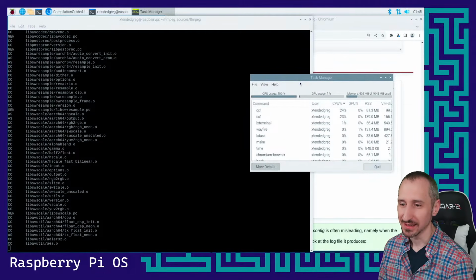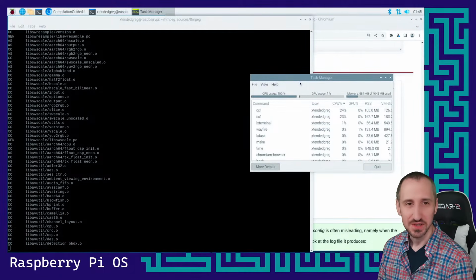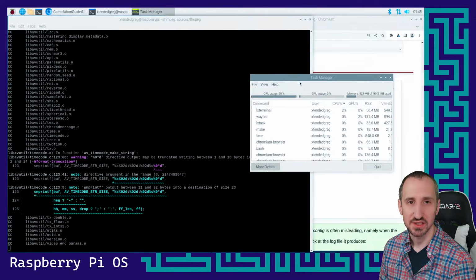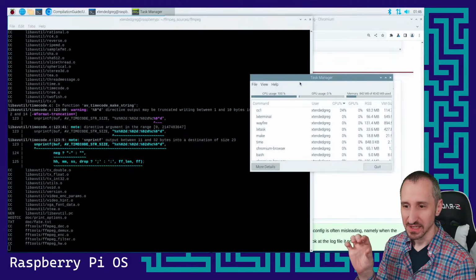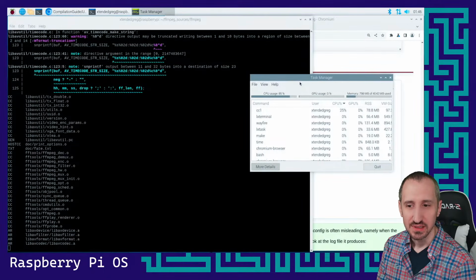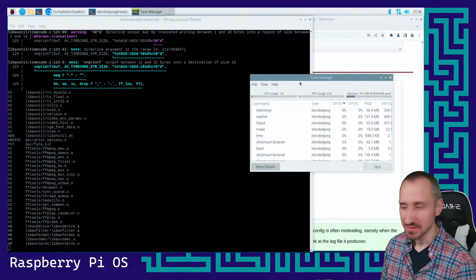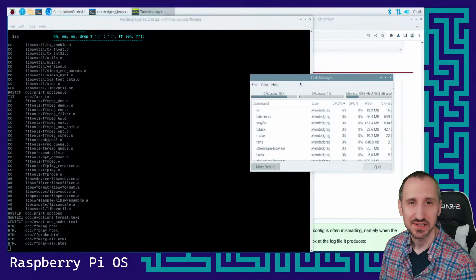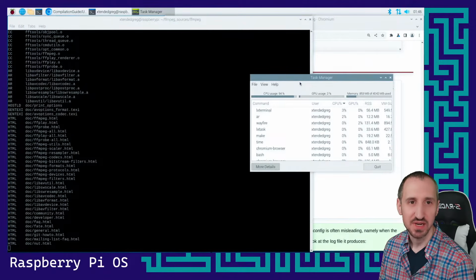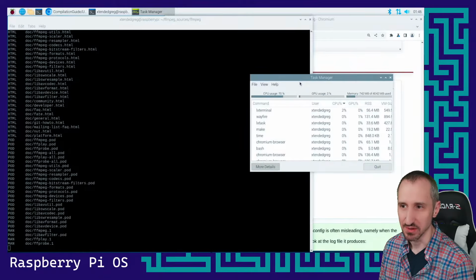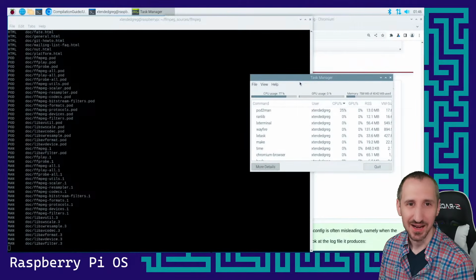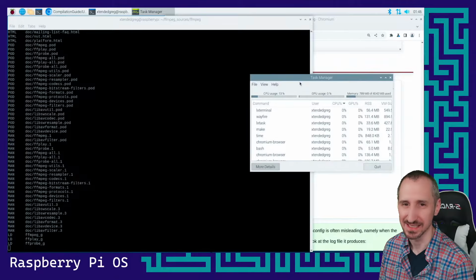So with the KVM itself, I could have just pressed buttons, but that was too easy. So I took the Pi Pico, built a web interface onto it, and from there made it so it would do the contact closure, or actually it just pulls a pin to ground, and that would change the input. Then I ran that to a Stream Deck, which I used for changing the shots, everything else like that, and that actually changes the title. So the Raspberry Pi OS title will change automatically based on what machine I have selected when I choose the new input. It was the cheapest way I could think of, because I was looking at other KVM solutions, and IP KVM solutions are really expensive.